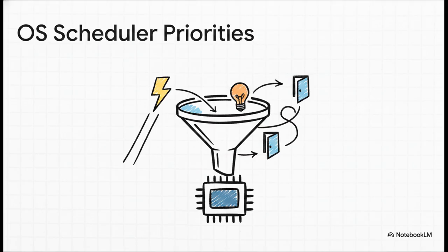The shortest, most critical deadlines, like our power failure, receive the highest priority. They operate at the interrupt level for extremely fast responses. Relaxed deadlines, like polling a door, operate at lower priorities on the clock level. The scheduler guarantees that if a power failure and a door opening happen at the exact same millisecond, the power failure absolutely gets the CPU first. So your math dictates the priority and the OS enforces it.